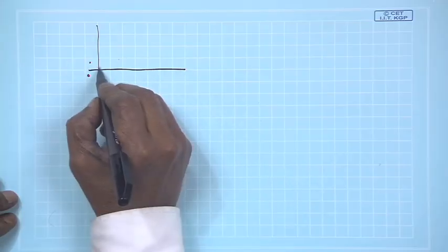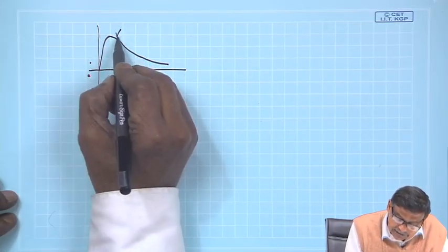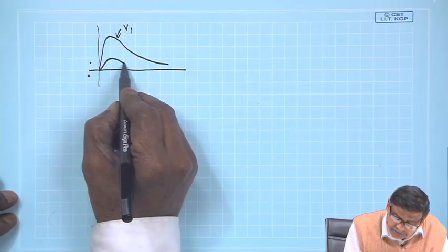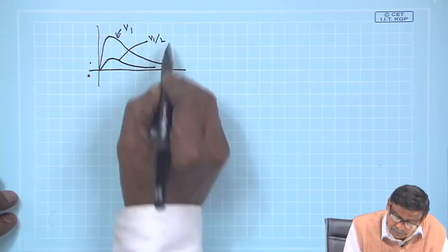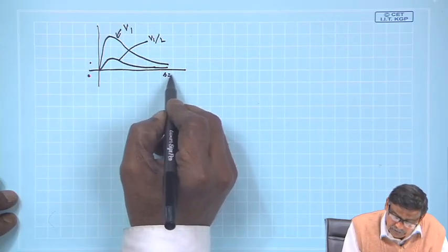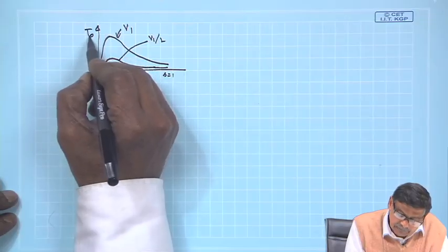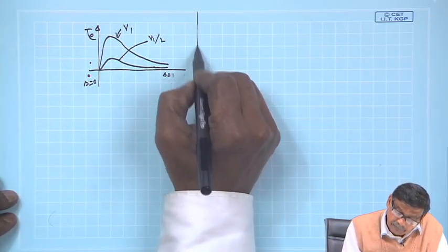very quickly drawing this. This is the torque slip characteristics at rated voltage, and if you change the supply voltage to half, it will become V1 by 2. Do not put S equal to 1, S equal to 0. This is torque, the T max, so that is the supply voltage variation.